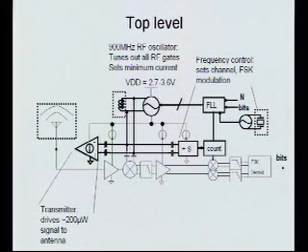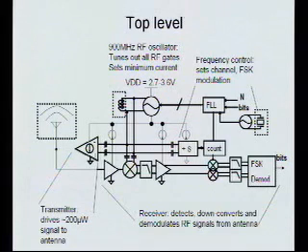But FM, or FSK as it's called, frequency shift keyed modulation, is the simplest to implement. And finally, we have a receiver to receive FSK signals and down-convert them and demodulate them to bits. So the overall goal here is to have only these off-chip components I've outlined, plus a battery, these 3 off-chips, and only talk to it in digital, sort of low-frequency digital. So just put in transmit bits, get out receive bits, nothing else.